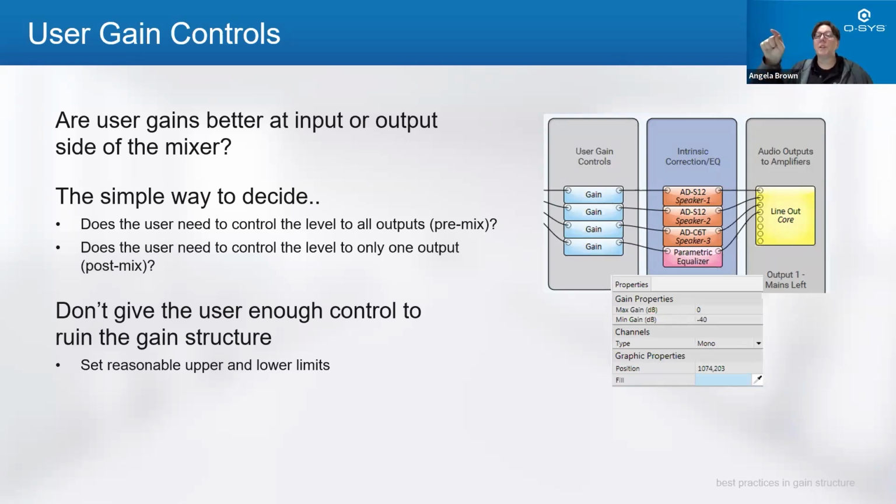So if they brought the music up for zone A, the wireless microphone all of a sudden was way too loud. So all I did was go into the DSP and reprogram it so that the music volume control was just the music volume control, and I didn't even give the user the output volume control. So be aware of that. Think about that deliberately. Go through that and take your time. And again, just be very, very deliberate with this.